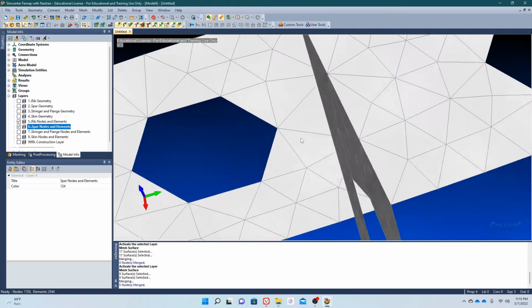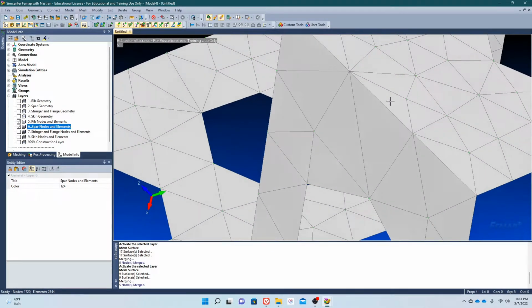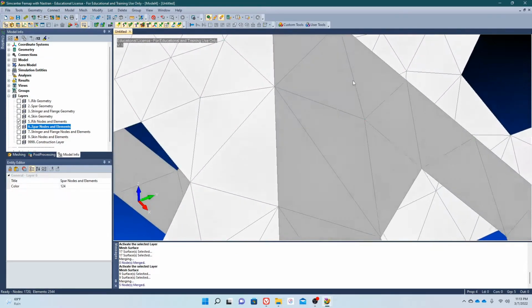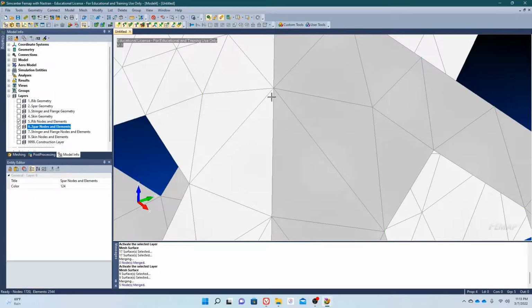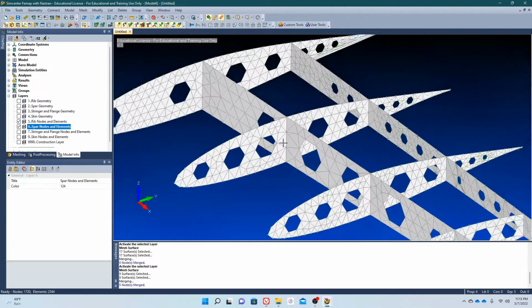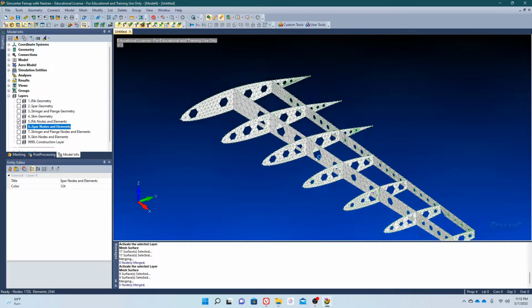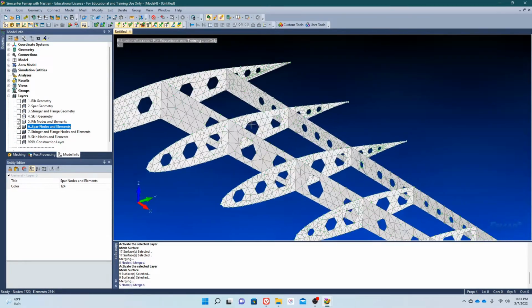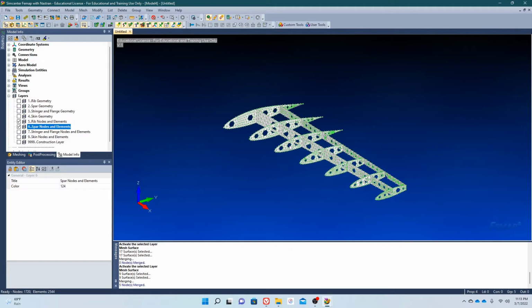That's how computational analysis works in FEA and CFD. So if we actually have elements that aren't connected via nodes, then we're going to be getting weird behavior, and we might see that in a second. But for now, let's move forward.